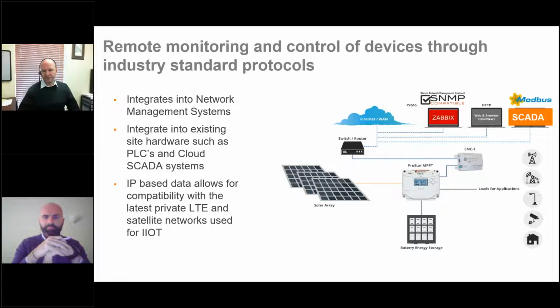Remote monitoring is critical with power management, because if you lose a load or your equipment, or the SCADA data is no longer being relayed back to where it's being monitored and you don't know why, it's good to have visibility of what's happening with the power system. Is the array providing proper output, close to its rated power levels? Is the battery healthy? Is your load being sustained day after day? Is the load being powered during inclement weather?